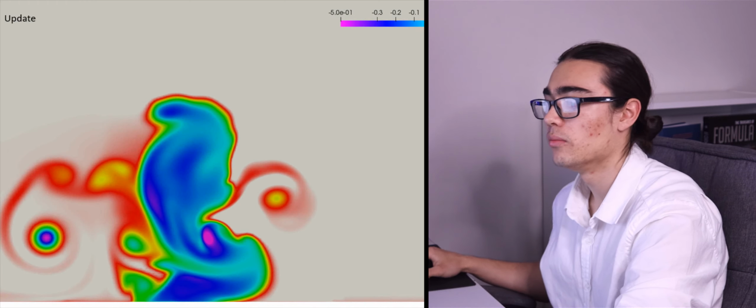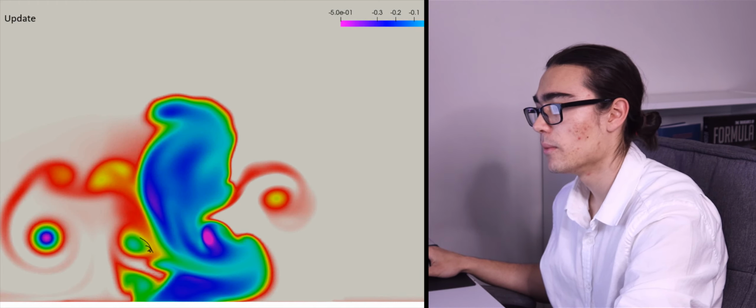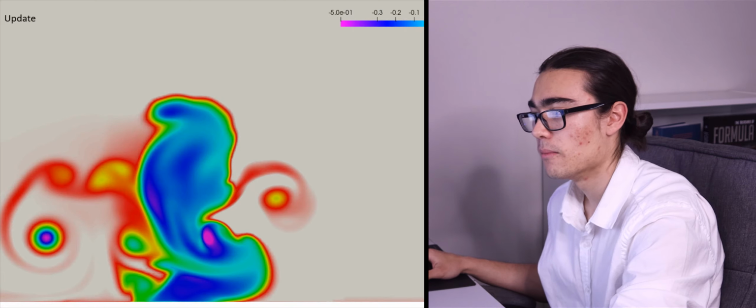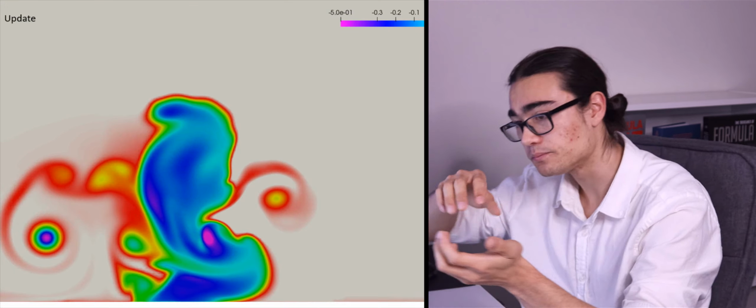Okay, now behind the tire, and you can see quite a large difference there. So we're kicking a lot more of the flow with this vortex, it looks like. Maybe a bit more flow attachment around the tire. This vortex is looking to work some of that flow outboard a little bit, perhaps due to flow attachment around the back of the tire. Maybe not, maybe we're in a bit of a transient situation and we haven't accurately modeled the problem. I'm not sure. We have made some relatively big changes, so I think that we can make some general assumptions, but we still need to be careful.